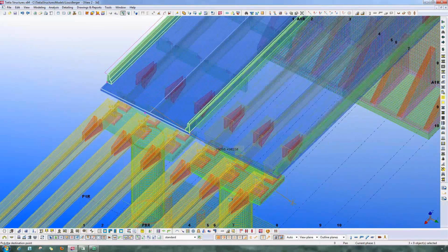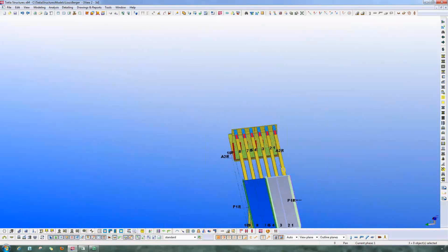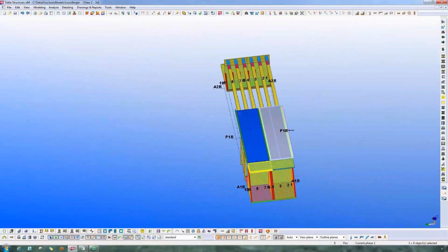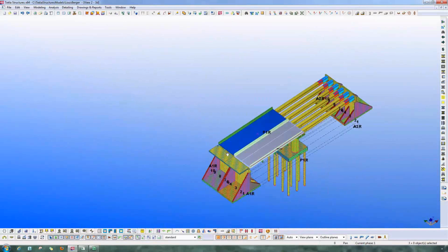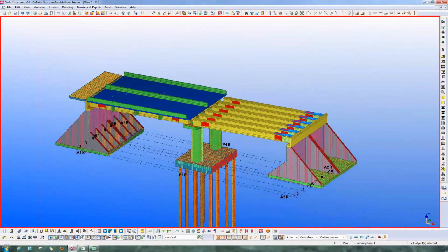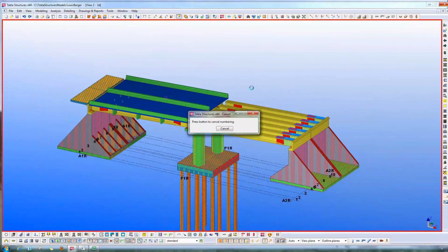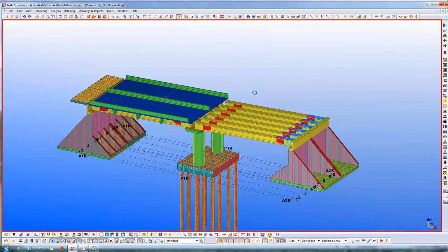Now we can see the half portion completely modeled with the text prepared. Now we can do the numbering, so that for each and every cast unit we can get the proper labels, and even for the reinforcement we get the bar mark number. So it's already done. So now we are going to open one of the drawings.